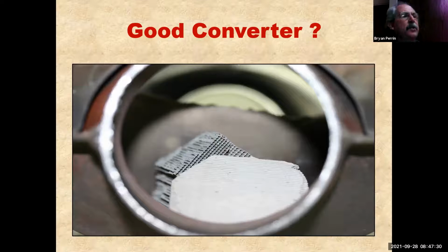And this next subject is a prime example of that. So we're going to shift gears a little bit out of the catalytic converter now. We've talked about how the CAT works, and we talked about OSC, oxygen storage capacity. Because I'm going to maintain that rear sensor at a certain voltage based on oxygen storage capacity, I can now use that rear sensor to control the mixture in the engine. And that is what we're doing with rear fuel trim. Rear fuel trim is pretty fascinating.